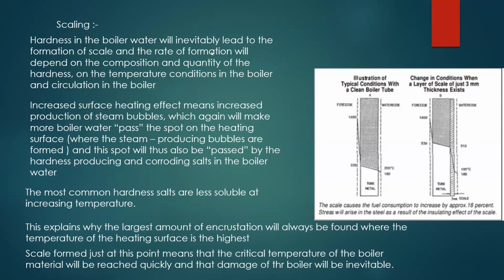Hardness in the boiler water will inevitably lead to the formation of scale. If you have either temporary hardness or permanent hardness, both lead to scale. And the rate of formation will depend on the composition and quantity of hardness, on the temperature condition in the boiler, and the circulation in the water.